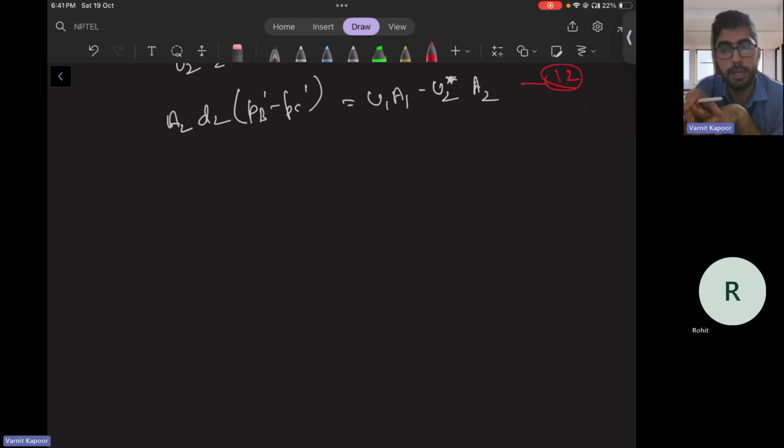So what we got here for cell B. Okay, so why are both the two equations the same? That means we do not have any additional equation. The two cells together are giving you only one equation. This is because both boundary conditions are given for velocity. As a result, there is no boundary condition for the pressure.